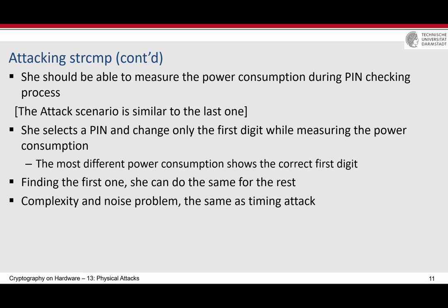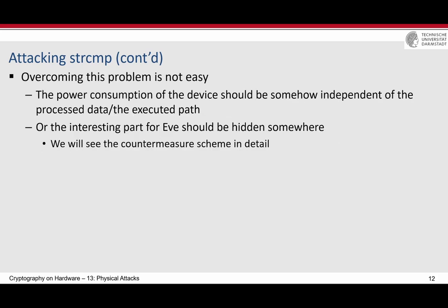But the complexity and the noise problem are the same as in the timing attacks that I explained. Overcoming this problem is not as easy as you think. It's not as easy as with timing dependency, because in timing you should just make sure that the timing is constant. But it's absolutely impossible to build something which has constant power consumption.